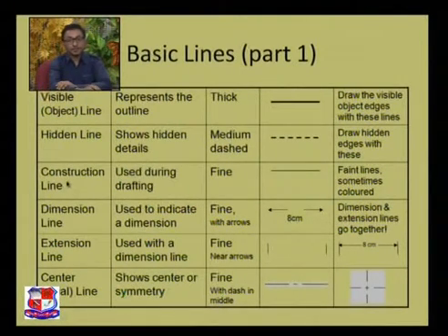Construction line. What is the use of this construction line? Construction line can be used to stretch the projections. When you are in orthographic projections, you will be drawing the top view from the front view, and the side view from the top view and the front view. So at that time you need to take the projections. You will get brief details about how to use this construction line in the chapter on orthographic projections, and you will have better practice over there.